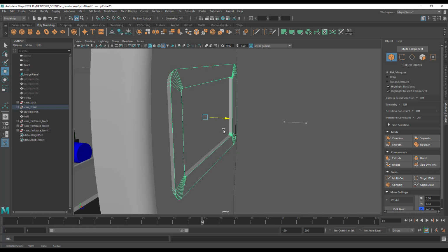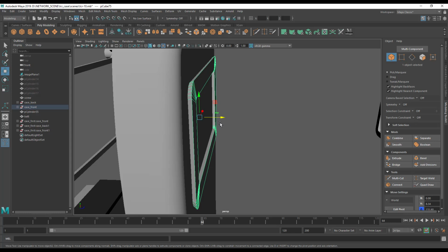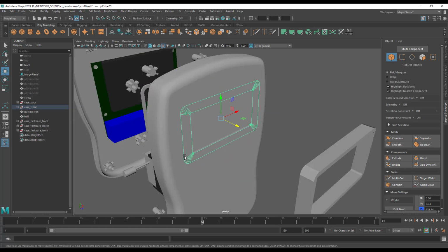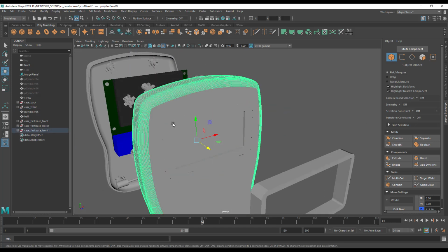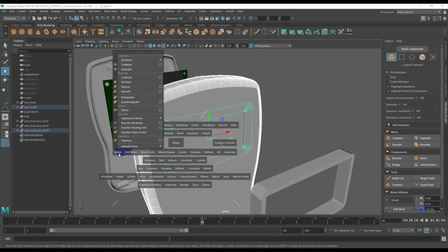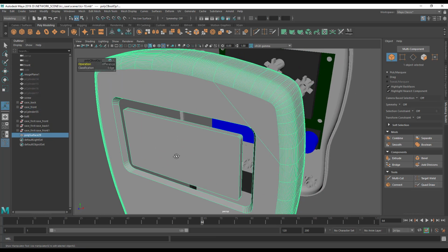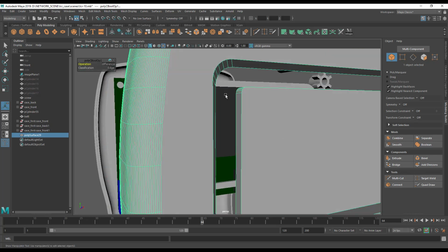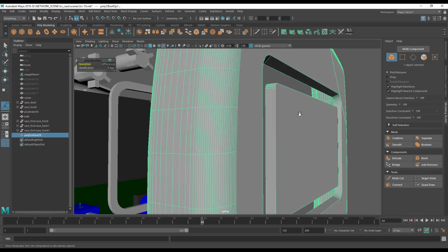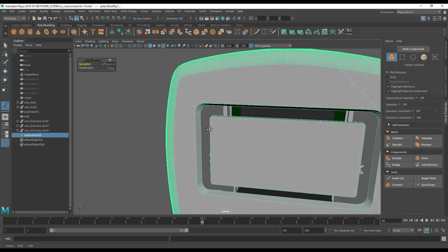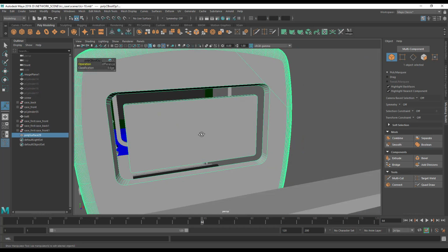So when we push this through now, make sure it's gone through the back. Done. I'm pretty confident that this will cut just fine. So mesh, where are we? Booleans and difference. Yeah, that did. And you'll see it's left a groove in here, which I think will look more attractive just slightly as a design aesthetic.